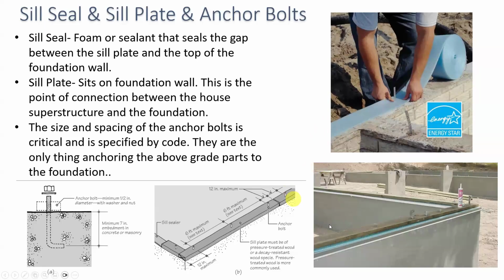So the sill plate sits on the foundation wall. It's typically pressure treated. And then the anchor bolts are specified by code because that's the only thing holding that house on. That's the only connection between all the wood structure above and the foundation.